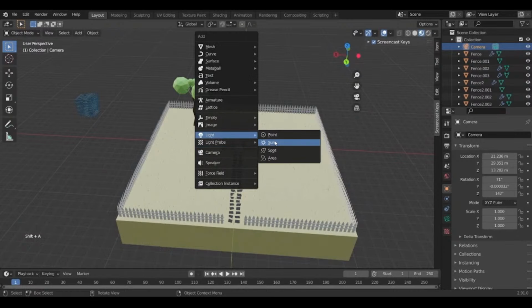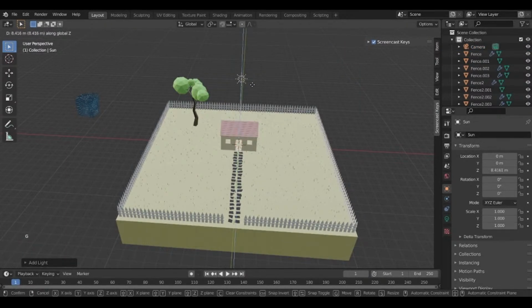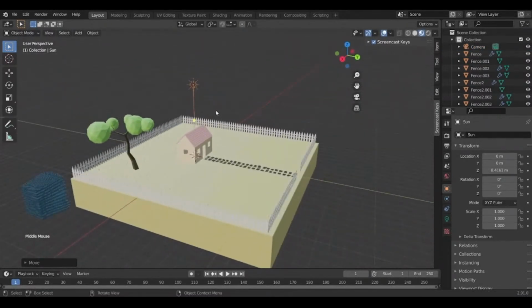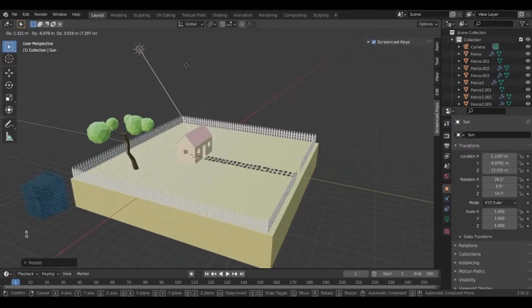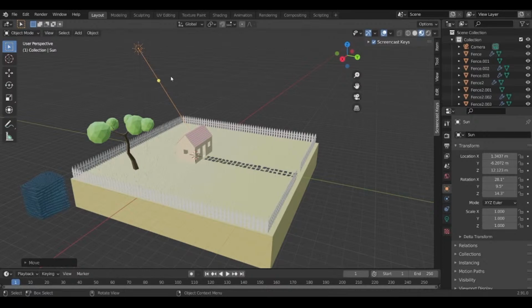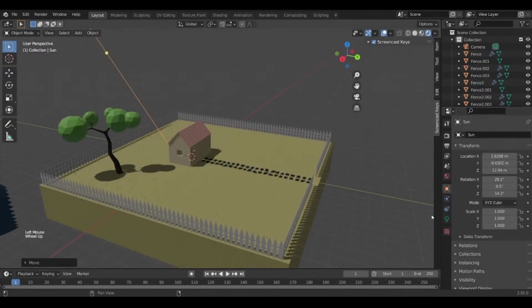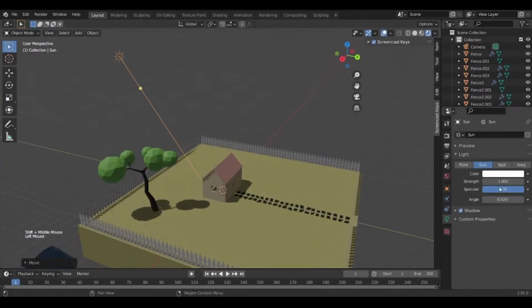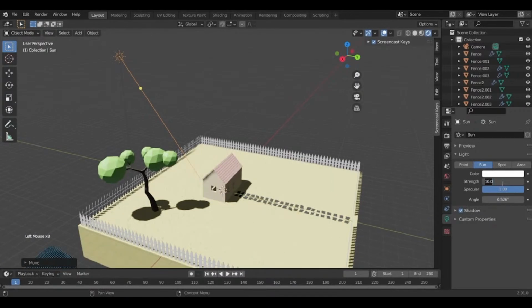Then you can render it, but there's no light, so I'm just gonna add a few lights around to show you how it looks. The sun. So there are different lights. The thing about the sun is that it directs light, same rays come from all directions just like the sun, but all from this angle. You can see how it looks in the render mode. I can increase the intensity here, light option, and then, too bright, so 8.